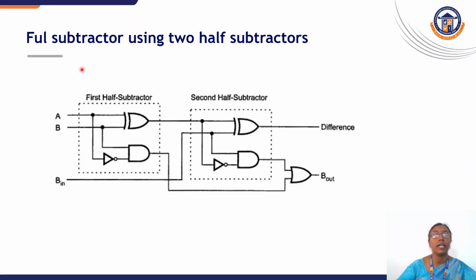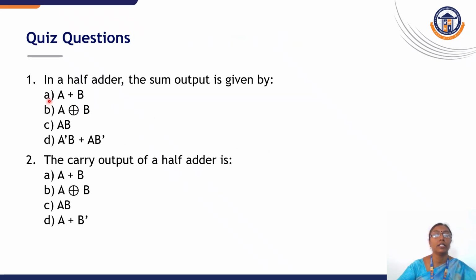Thus, like the full adder, the full subtractor can also be constructed using two half subtractors as well as one OR gate. So with this, we have learnt half adder, full adder, half subtractor and full subtractor. We can have some quiz questions.